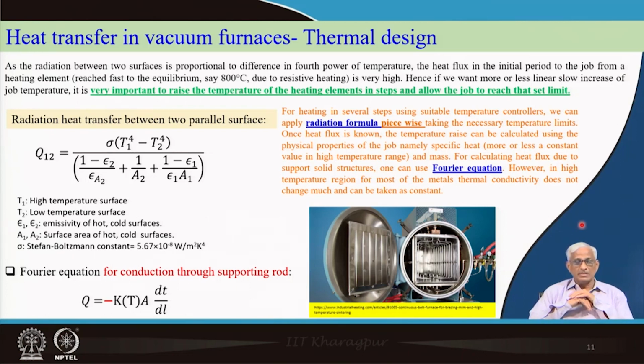Once you do all that, still a lot more issues are there, heat transfer issues, heating elements, after all these furnaces. Same thing in substrate heaters in semiconductor manufacturing. But these things are not much in particle accelerators of ultra high vacuum. There will be some heating for degassing only, otherwise it is a cool process. High voltages will be there, high magnetic fields will be there. That application is a different game. At that time system design should do what? How do you separate the cryogenic environment from the vacuum, etc.